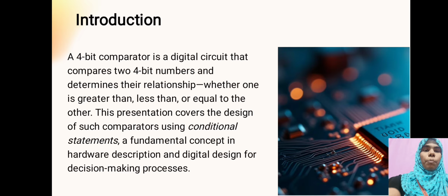A 4-bit comparator is a digital circuit that compares two 4-bit numbers and determines their relationship, whether one is greater than, less than, or equal to the other. This presentation covers the design of such comparators using conditional statements, a fundamental concept in hardware description and digital design for the decision making process.